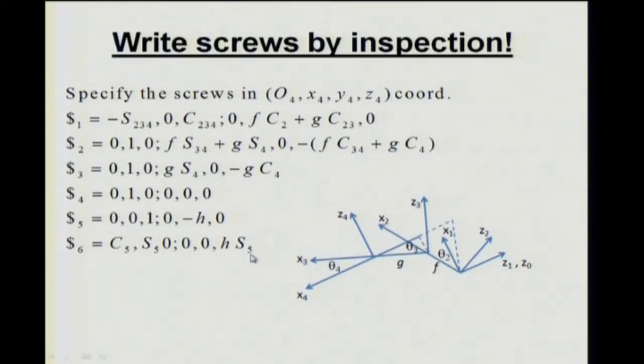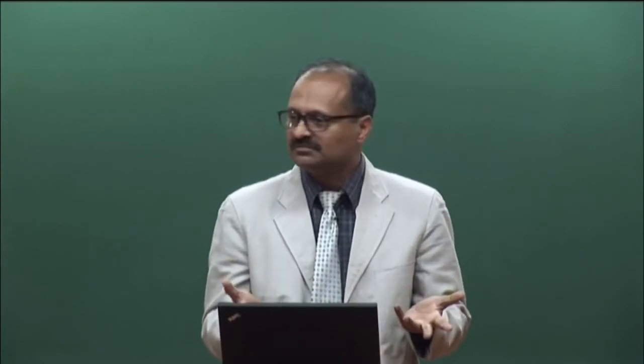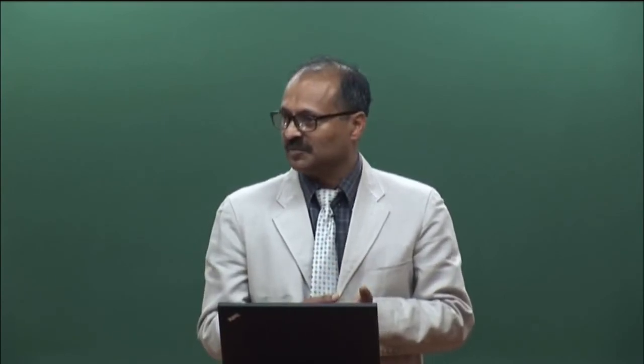So this is just magnificent. I don't have to do DH parameters, right? And what I have there is the real link parameters, which is, this is G, this is F, and then there is H, which is down there. So essentially the three major link parameters, the link lengths, which you can physically measure, they are there, and the angles are there, and I can measure them. And these thetas are the joint positions. So if you take the derivatives, I am in business.